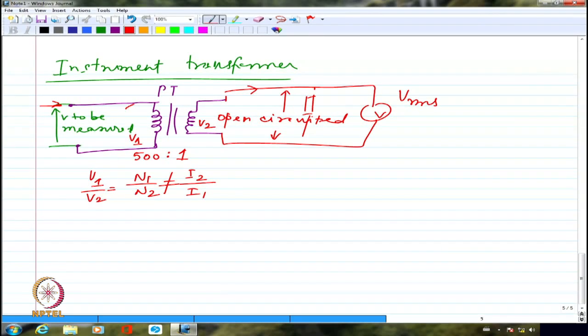You're just measuring the voltage. You don't want to connect your voltmeter as a load, do you? So, if you don't want to load it, you better not draw a tangible current. The current drawn should be as minimum as it can be. So, I am telling that it has to be as good as an open circuit. That's all. Got it?